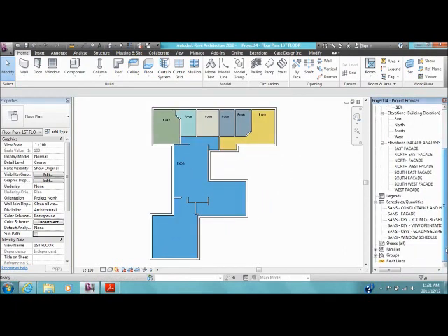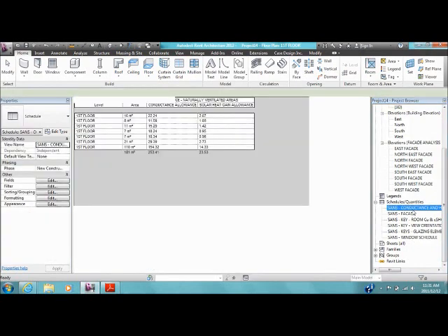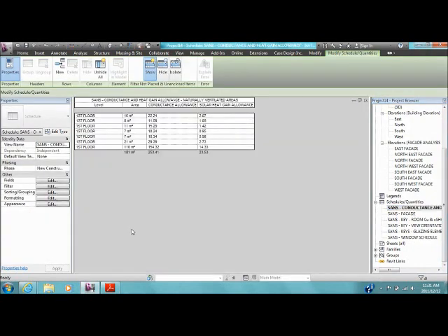Alright, so there I've created my individual rooms. If I now go and have a look at my allowance schedule, there it simply calculates it out. You can see 181 odd internal area there. Okay, so notice my values here for the conductance and the solar heat gain, 253 and 23.